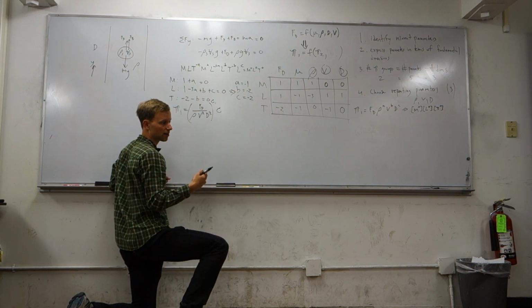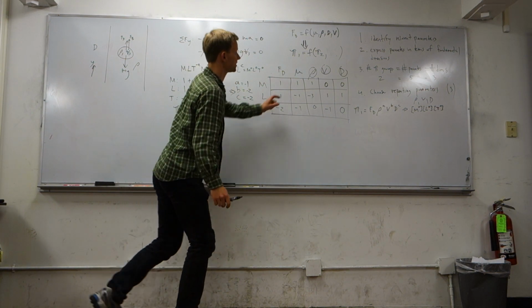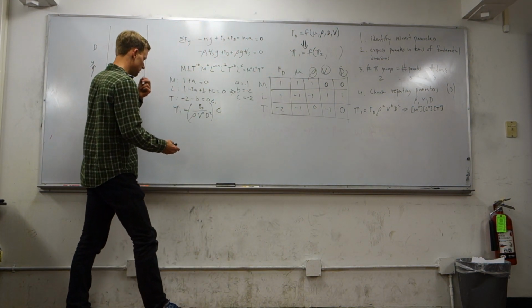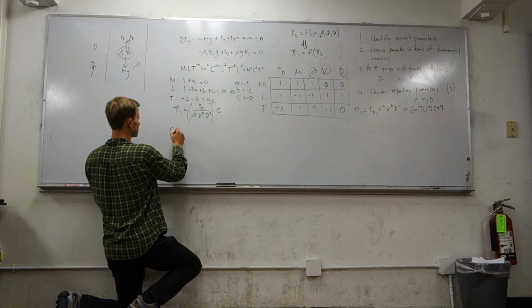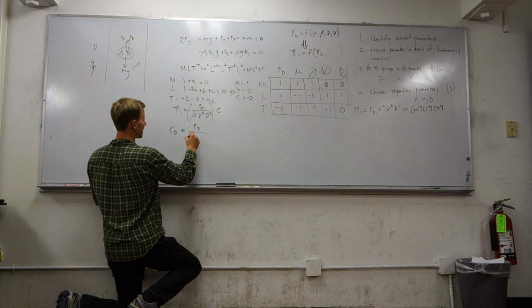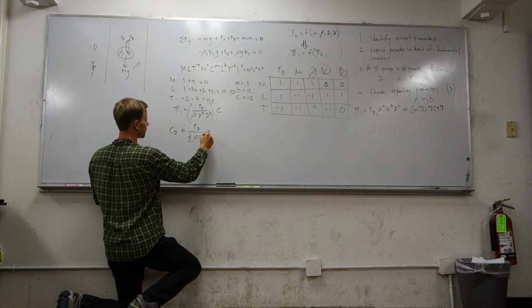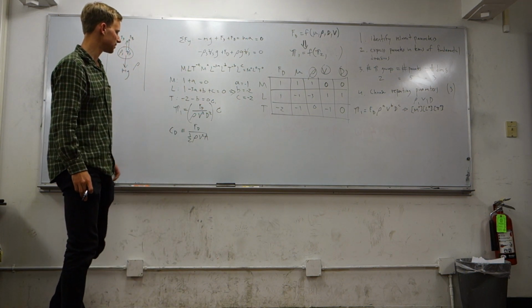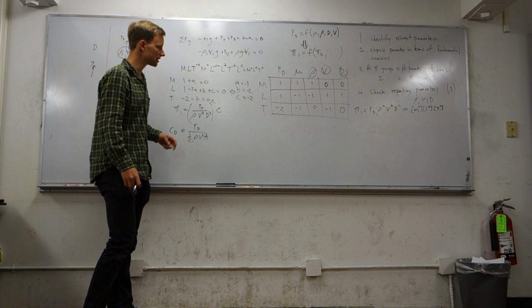But in order to use the functional dependencies that someone else took experiments for, we want these pi groups to be known quantities. And so the drag coefficient c sub d is defined as the drag force over 1/2 rho v squared times A, which is the frontal area of our object. We've seen this in previous labs. So this is pi 1, let's get pi 2.